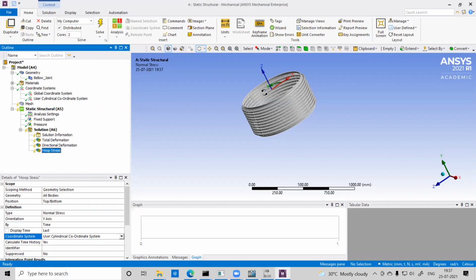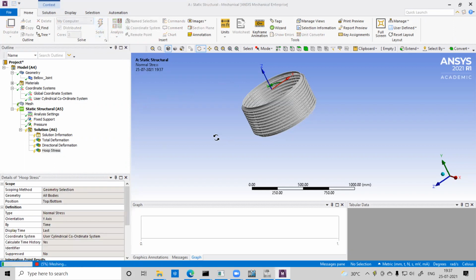When we design vessels subjected to pressure, we design for axial stress as well as hoop stress, circumferential stress. So circumferential stress is the main thing when something is subjected to pressure. But I don't think we can solve this problem because the mesh size is now 500 millimeter, right? This one is a very complicated structure, it creates many nodes.